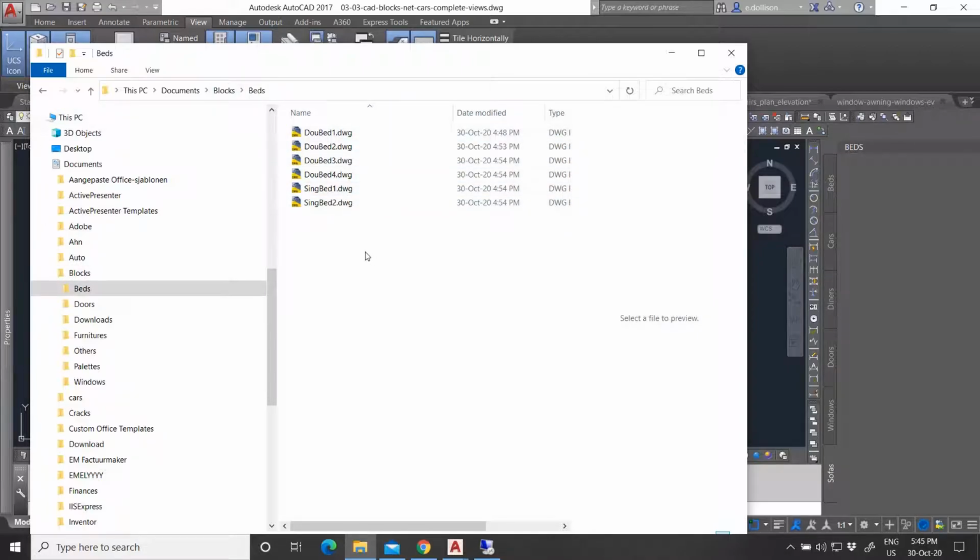And it is very important to do this well before you even import it into your tool palette, it has to be in the correct location you want it to be, because the tool palette will refer back to your local computer, or it will have the path on your local computer.